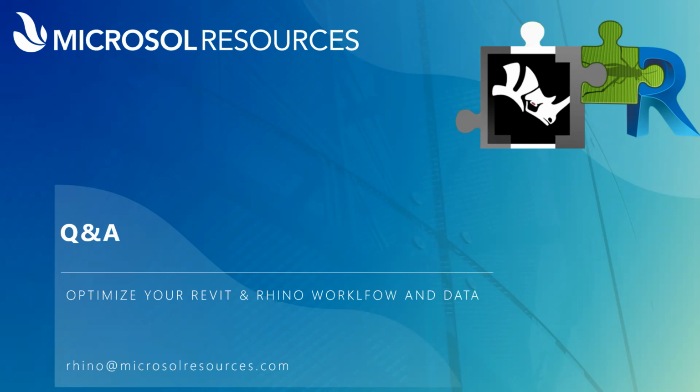Yeah, and you mentioned that PyRevit can run Grasshopper definitions that you have created inside Rhino.Inside.Revit. One really important aspect when you start developing for your company's deployment is how you get these tools into the hands of people that want to use them but don't necessarily need to know exactly how they work. PyRevit is a really good solution for that because it has this concept of bundles, the tools that you add to your Revit UI. Inside a bundle, you can have a Python script, a C# script, a Dynamo definition, or a Grasshopper definition. So different things can be inside of it.